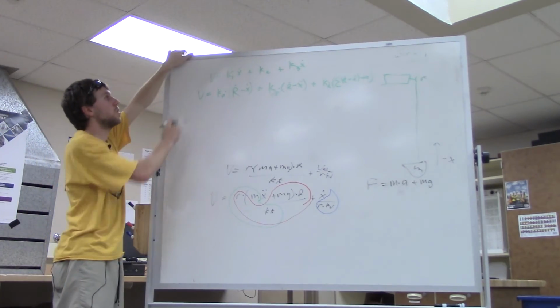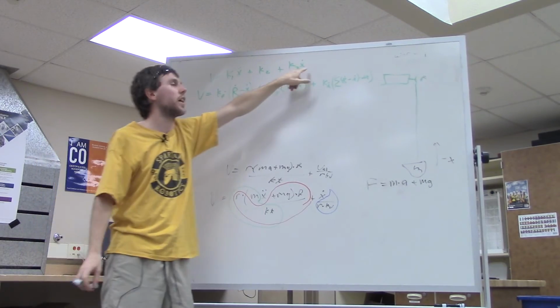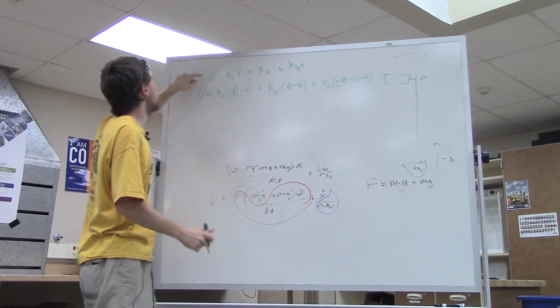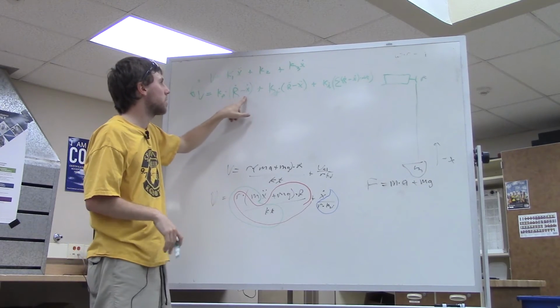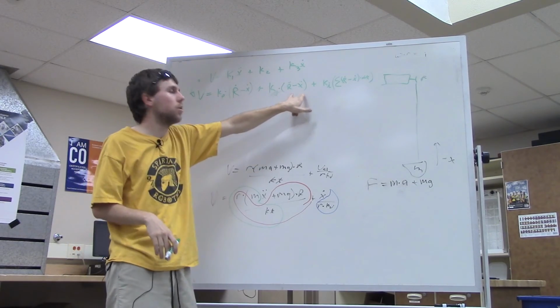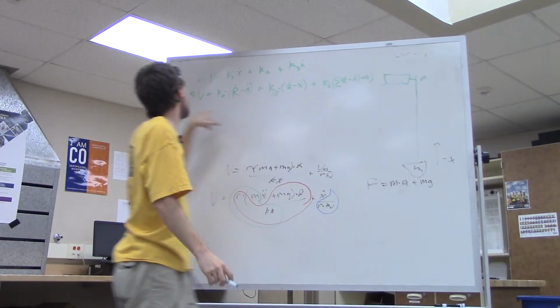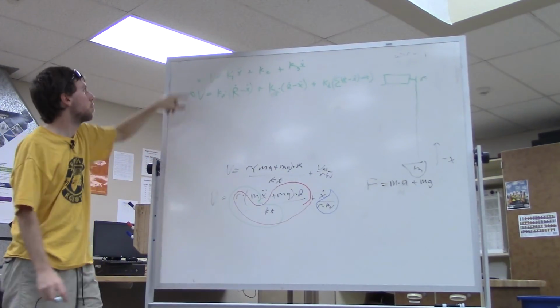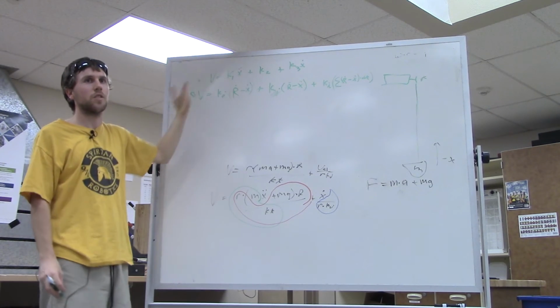So what we'll want to do is have a time step. Actually, we should probably do this in the other order. So we start out with some initial state x dot. We're going to compute some derivative term. We have our error, we have some integral, so we can compute a voltage. Now we can plug this voltage into here, and then we can integrate for a time step. And that gives us a new velocity.